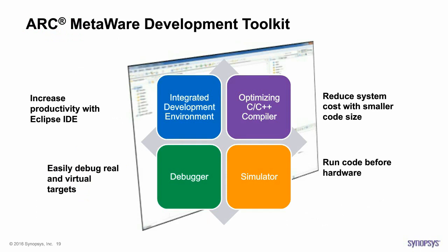So the MetaWare Development Toolkit has been developed over the last 25 years, and in recent years has been fully optimized to support the ARC microprocessor capability that Synopsys offers, which we use inside of the Vision processors. This is a very efficient processor, supports C or C++. The toolkit also includes a full debugger and instruction set simulator. It's a nice environment for developing the C or C++ kernels that you're going to run on the Scalar CPU.